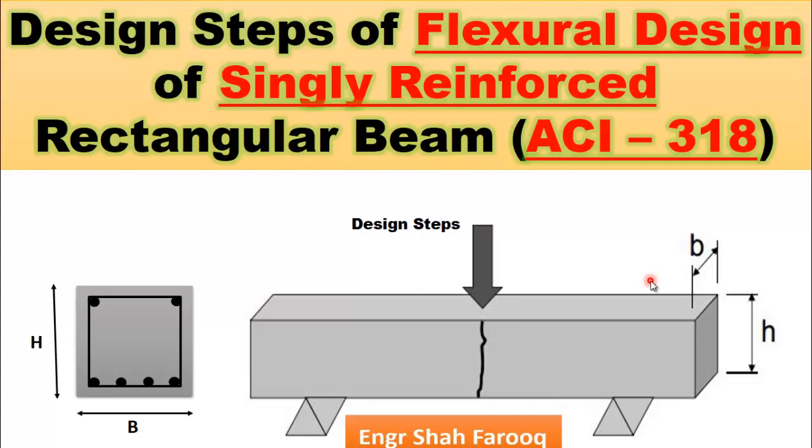There are different methods to design a structural member like beam, column, slab and foundation. To design a structural member, you need to follow certain design codes like British Standard Code, ACI American Concrete Institute codes, Indian Standard codes or Euro codes. Today we are going to start our discussion about flexural design of beam on the basis of the most commonly used design code, ACI 318. Here ACI means American Concrete Institute and 318 are a collection of provisions which govern the design